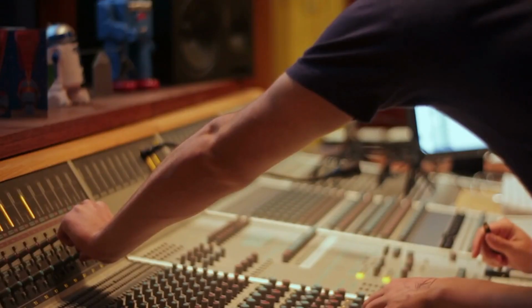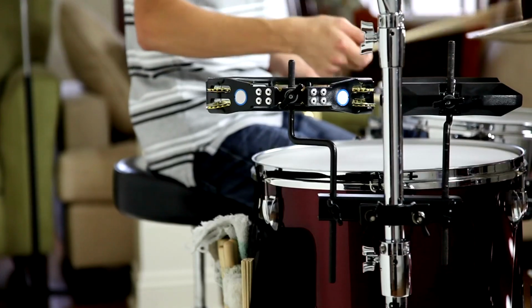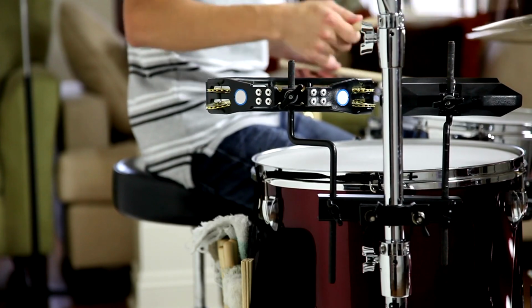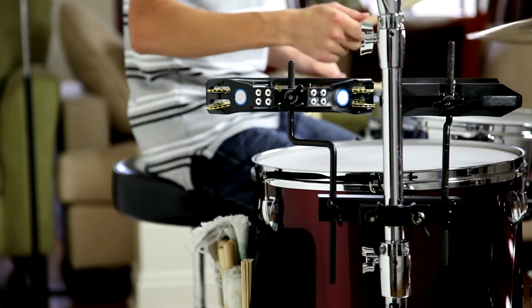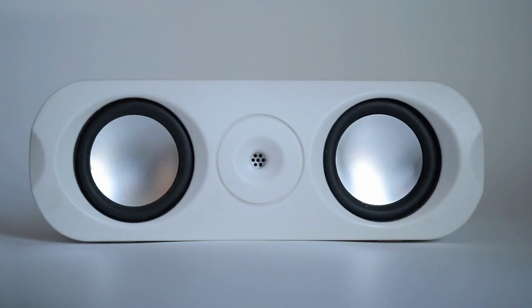Soundproofing for specific studio spaces. Different studio spaces have unique soundproofing needs. For example, a vocal booth requires a combination of soundproofing and acoustic treatment to create a quiet, controlled environment. A drum room, on the other hand, may require more extensive soundproofing to contain the high sound pressure levels produced by drums. In these cases, using a combination of techniques, such as adding mass to walls, sealing gaps, and installing floating floors, can help achieve the desired level of sound isolation.